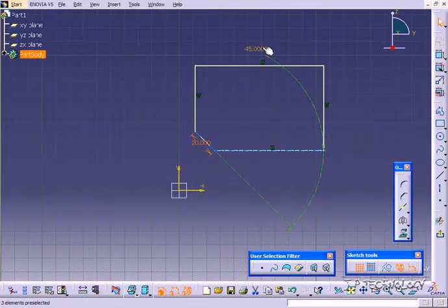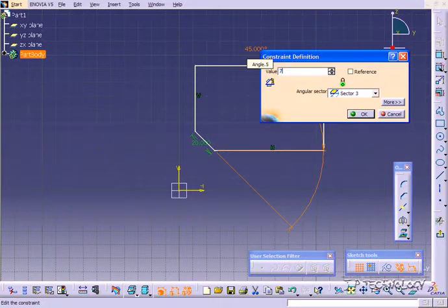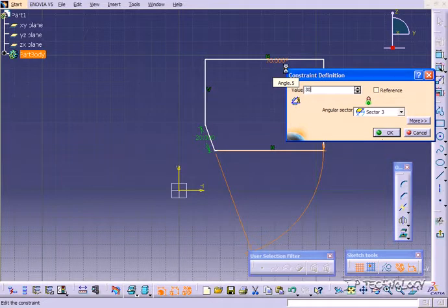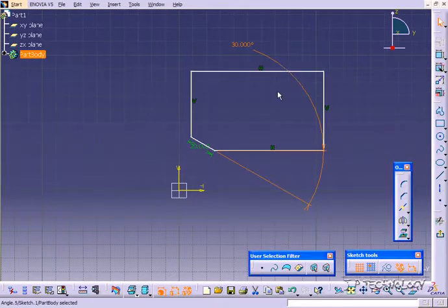And you're also able to change the angle that it's at. Automatically, all the chamfers you're going to make are always going to be at like a 45, just like this. Now you're able to change it to, say, a 70, or you can change it to a 30, and you'll see that it does accordingly. It'll change the size of the sketch and the angle. So let's keep going around, and we'll do some more chamfers.